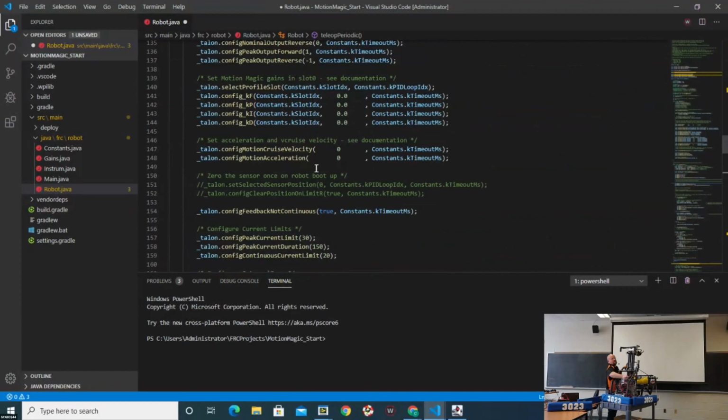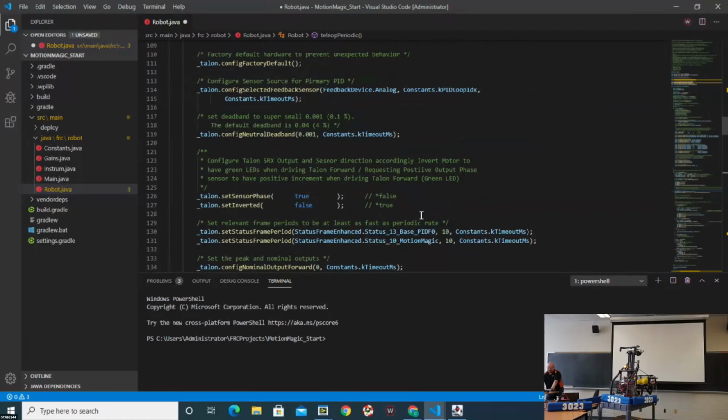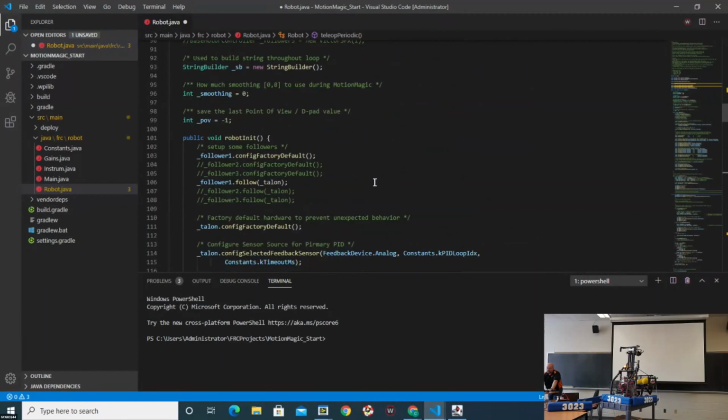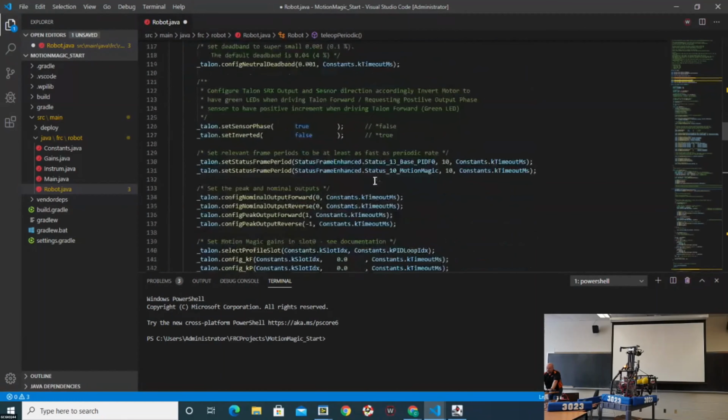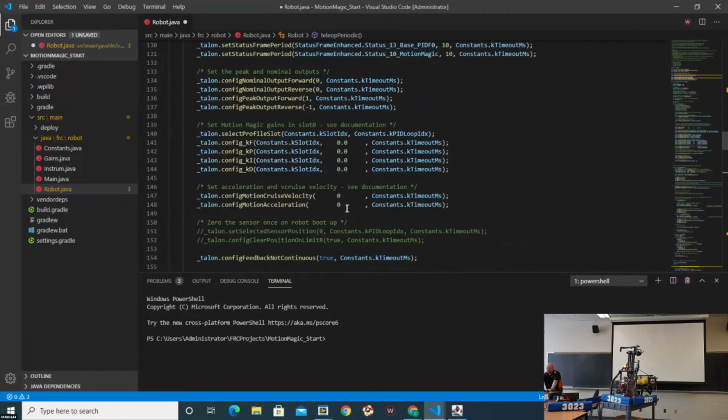I thought the robot was on, so I'll shut it off. Wait a second here for the robot to boot up. The key while this is booting up is to go in here and configure this sample code just for your robot: the CAN addresses, the joystick controllers, and zero all these variables because we're going to calculate those in a minute.